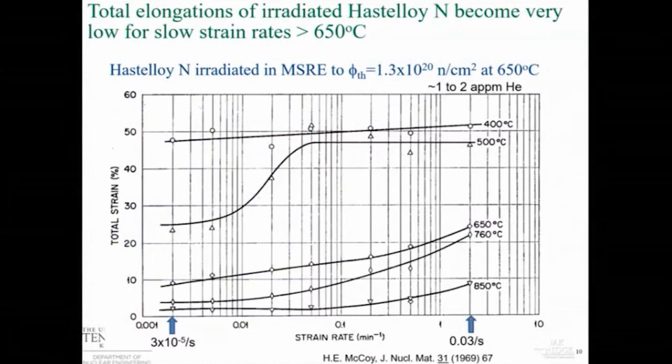They put a Hastelloy N sample in there, and so it was sitting unstressed. So that's a bit over-optimistic of the real case, running at 650 degrees centigrade. Then they came out and they tested a bunch of these samples at different test temperatures that you see here and at different strain rates.